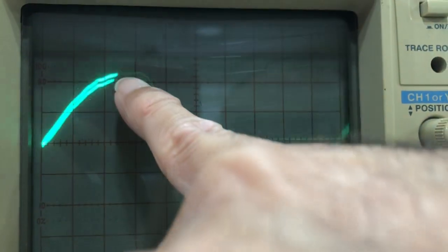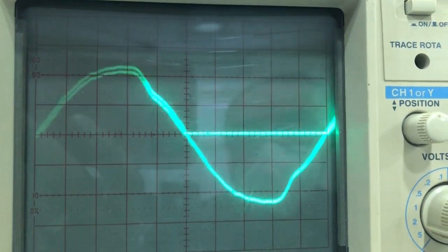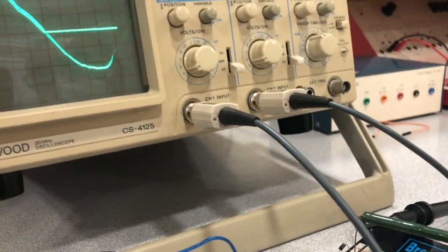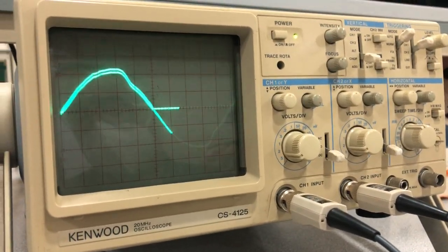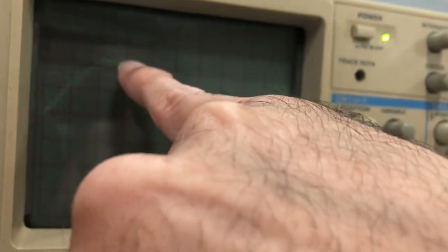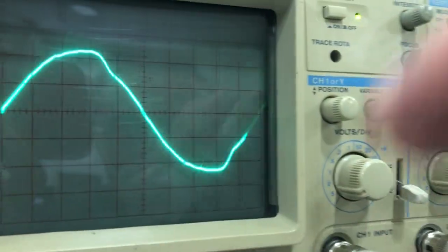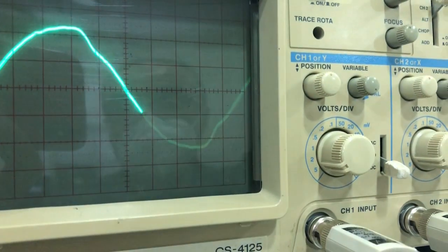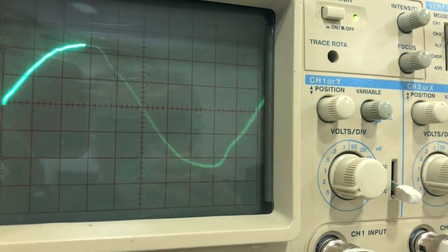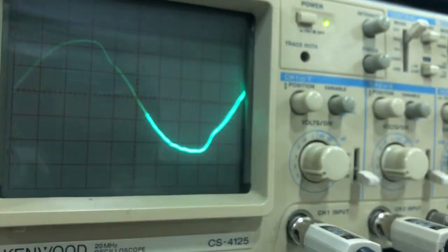Now, obviously, I have a voltage drop here on the output of the diode because it's losing, as we said, 1 volt at 1 amp. But here our load resistor is 91 ohm and it's going to draw a little bit more than 0.1 amp, because if you notice, the output here is more than 10 volts. I'll turn off channel 2 and focus on channel 1. My output is not only 10.6, because I have 5 volt per division, so maybe the electricity coming is 220, maybe 230. Anyway, the peak of the transformer is more than 10, because 2 divisions are 10, because I have times 5.